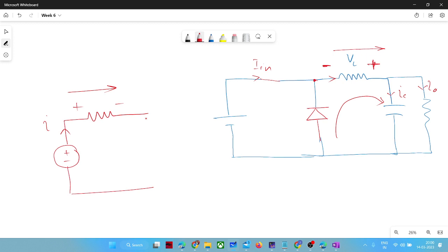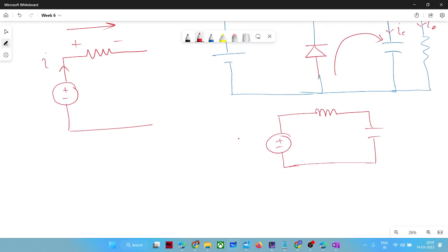If the switch is turned off for an infinite period of time, first of all, in the time it requires to dissipate its energy through the resistance, the inductor will be discharged and your current will be zero. But if there is no load, suppose you have only L and C, and C is also fully charged and your inductor is fully charged, this condition is called a resonant condition. Your current will oscillate with the frequency 1 by 2 pi root LC, and it will keep oscillating, right? The capacitor will be charged, then it will discharge across the inductor, and the same thing will happen repeatedly.